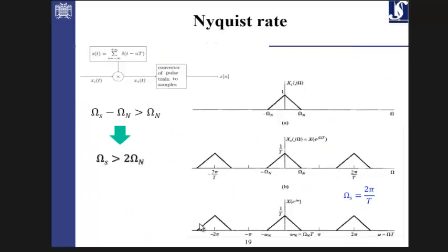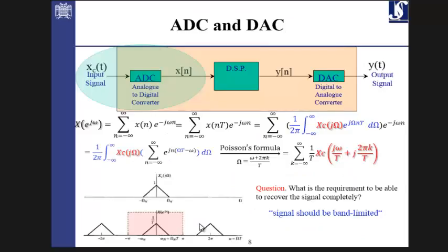I have a question. Regarding the limit of the DTFT, here we have omega n T, right? Yes. I don't get it here in the red part, in the last part, we have x c of j omega over T. So shouldn't it be omega over T rather than omega T, the bound of my signal?